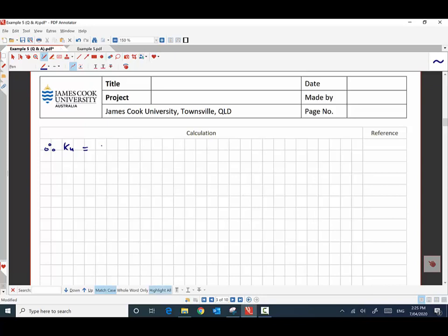The area of steel in tension is 3.6. Now for writing epsilon sc, we can write it in terms of concrete strain as we derived before, 0.003 concrete strain, and d is 430.